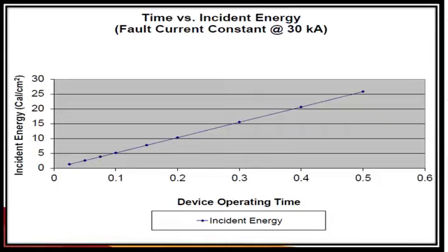Similarly, for your existing plant, if you plan to implement NFPA 70E and carry out this incident energy analysis for your complete plant, your consultant will perform the study and identify the locations where there is potential for reducing the incident energy from 40 cals per centimeter square to 8 or 5 cals per centimeter square, by only doing this device coordination properly.